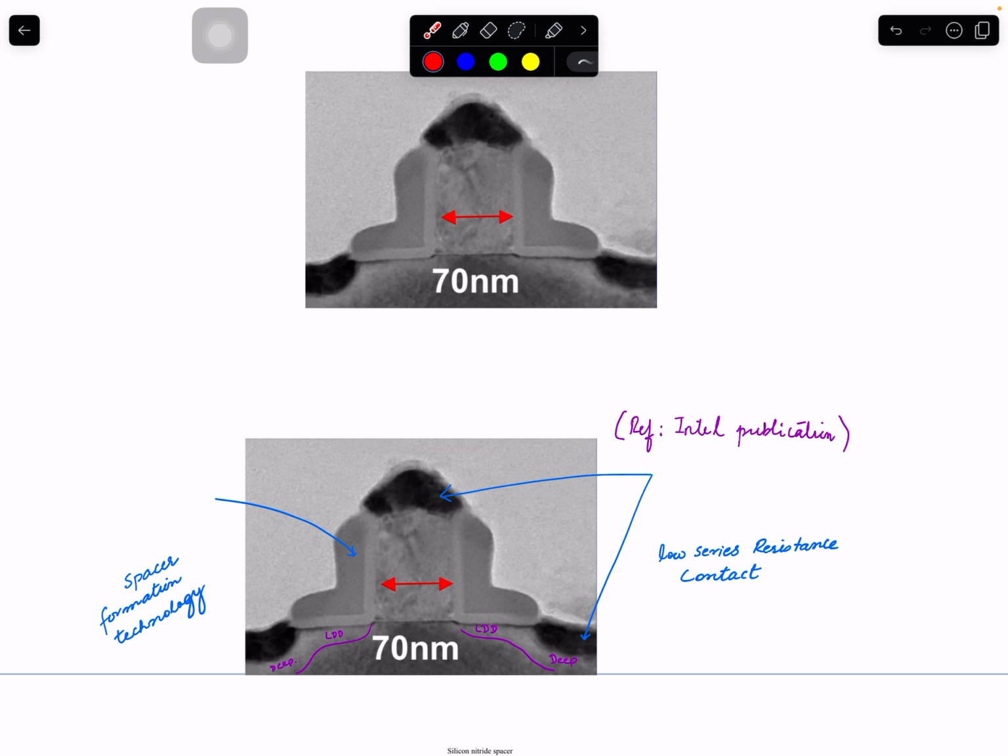So, yeah, I just explained that. After I explain the short channel effects, I will explain what was done from 500 nanometer to 130 nanometer and beyond. Beyond that, some more things were done, but for these process nodes, one of the things done was this, which gave the diffusion this type of shape. But let's not worry about that. I think this explains the same thing I already explained. These are low series resistance contacts, and these are silicides basically.